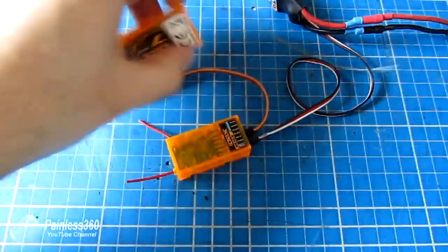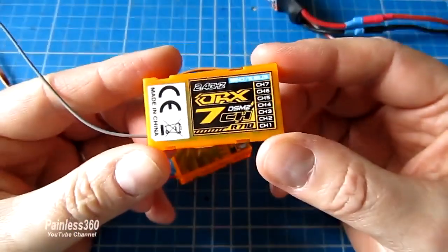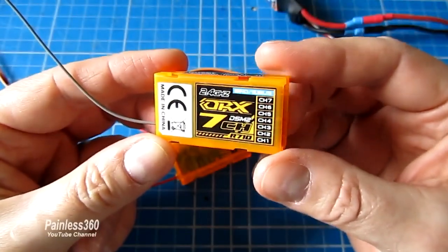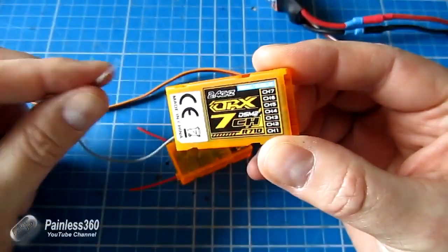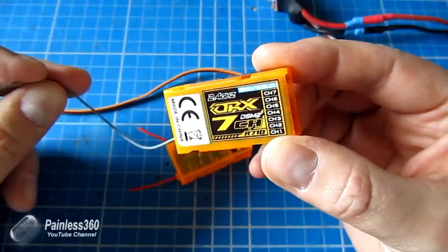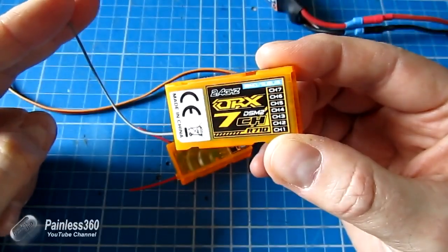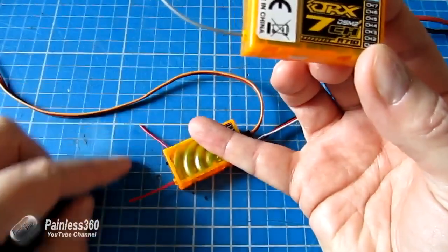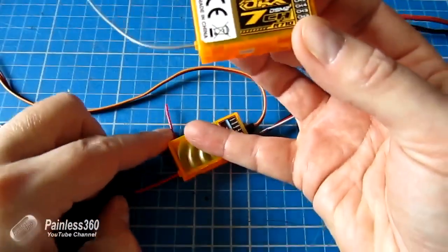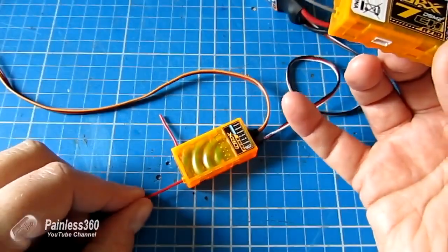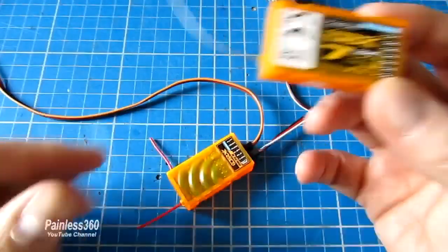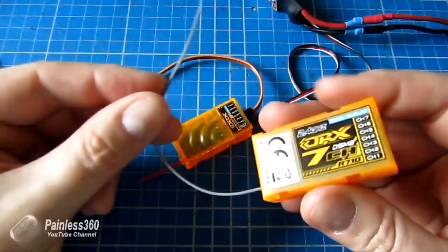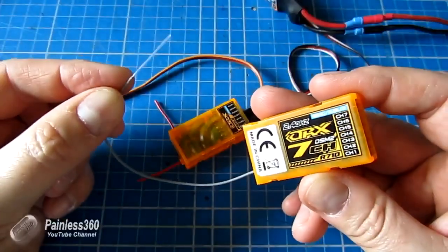Pretty straightforward stuff. Some of the receivers though, like this one, this is a 7-channel receiver from Hobby King. This one interestingly doesn't have Failsafe, so you have to be a bit careful, but it has a longer antenna, and that's handy if you're going to put it inside something like a carbon fibre plane or chassis. These little stubby aerials are fine, and the reason there's 2 is it gives you what's called diversity, so depending on the orientation as you fly the craft around, it gives you 2 chances of getting a good signal. With this one, this big long wire is supposed to come outside of a carbon fibre frame.